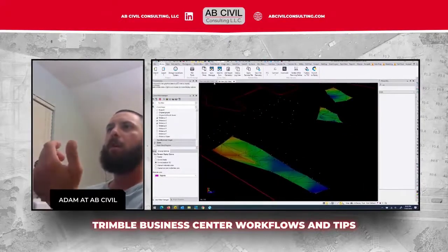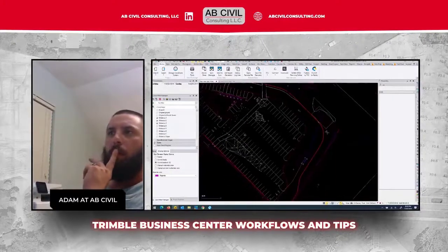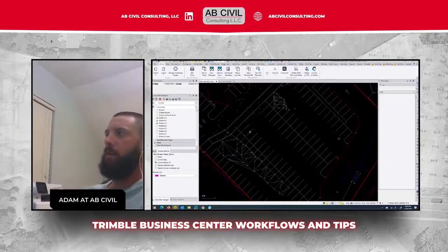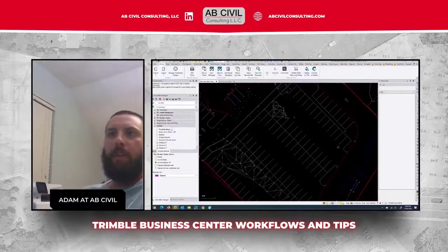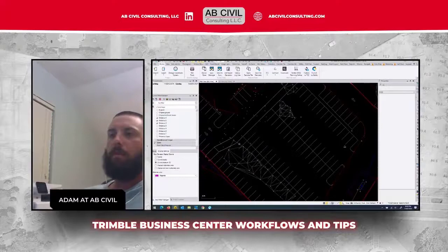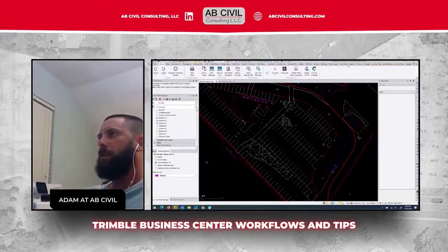I made the surfaces. The first thing I had to figure out was that these were all undercut areas. It was unsuitable material, and the contractor was subject to compensation for all of it. So the first thing I do is figure out what offset the subgrade was supposed to be cut to. I don't make a lot of subgrade models, not for construction at least.